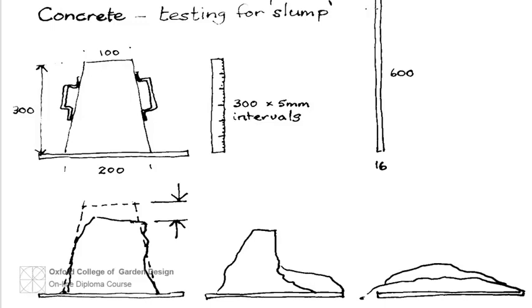The workability is measured by the slump of fresh concrete and is quoted as a figure, for instance 75 millimeters. In the absence of other instructions, a 75 millimeter slump is the workability which ready-mix plants will supply. Slump represents the amount that a cone-shaped sample of fresh concrete sags under its own weight when it is turned out of its mould.